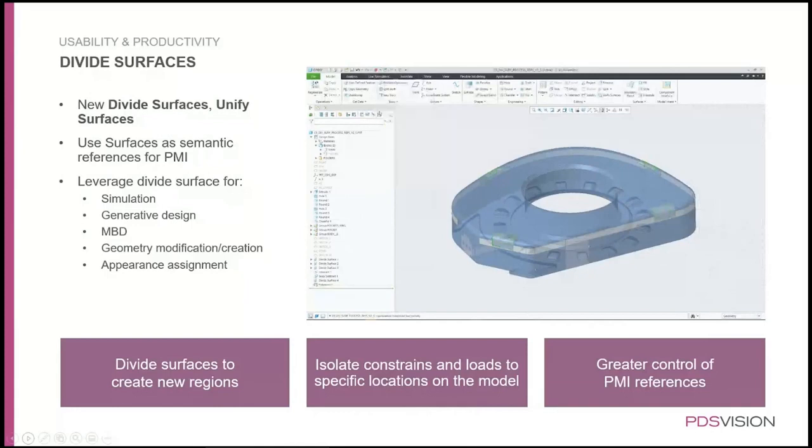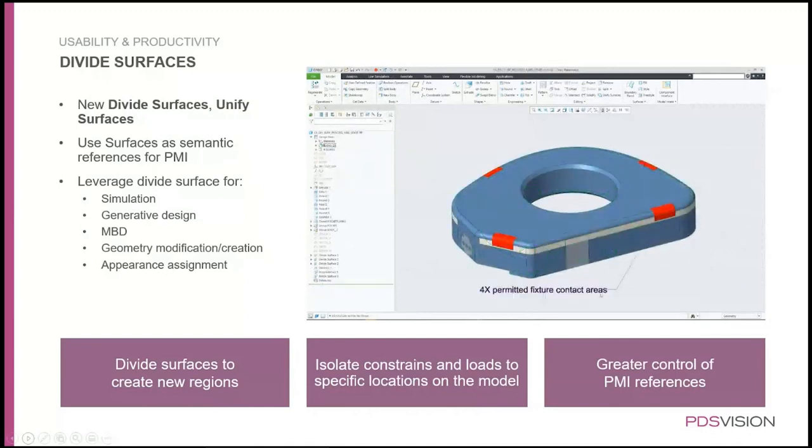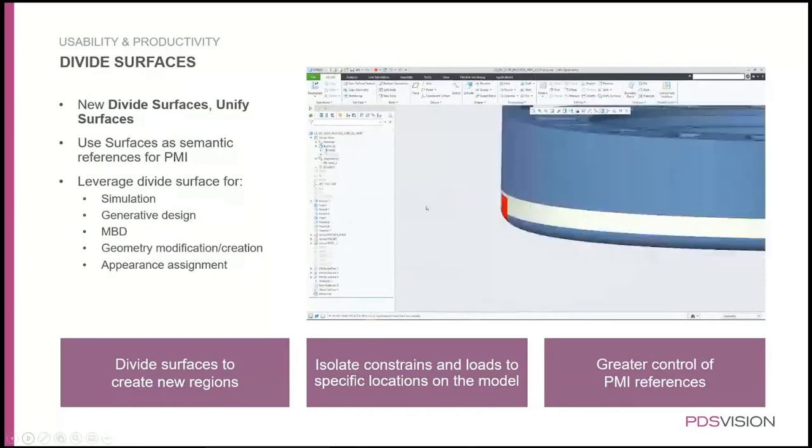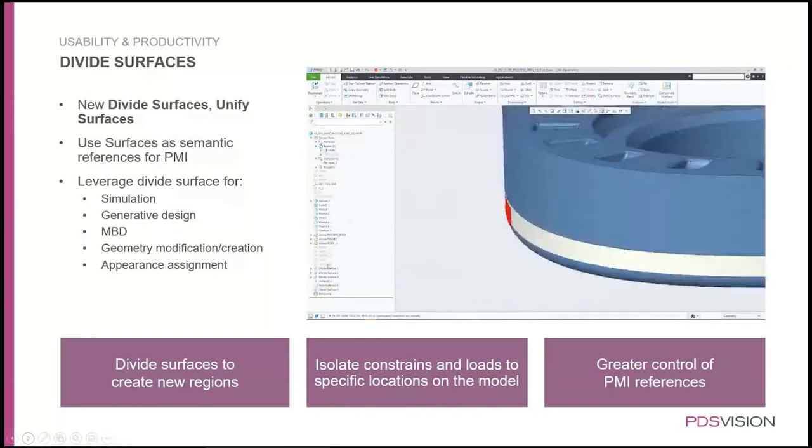And then again, we do some coloring using that reference feature. Bingo. And then at the end of this video, what we'll do is use the divide surfaces feature to write some text to the side of the thing. And of course, you can just split the surfaces and make it available like that. Or, on the other hand, what we can do is make it a geometry to extrude or basically cut. And as you can see in there, we wrap the text around the piece.